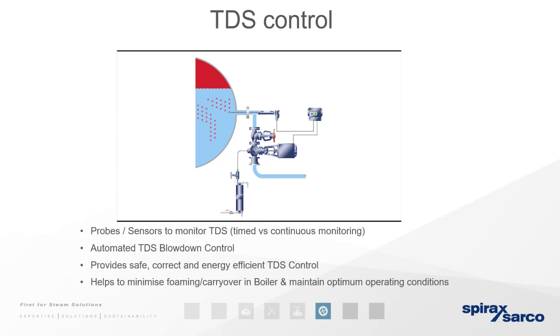The TDS can be controlled manually by treating a cooled sample of water with chemicals. And when a high concentration is found, a volume can be bled away from the side of the boiler, as seen here, at which point the level control probe registers this demand for water in the boiler, and the operated volume of hot water is supplied from the feed tank.